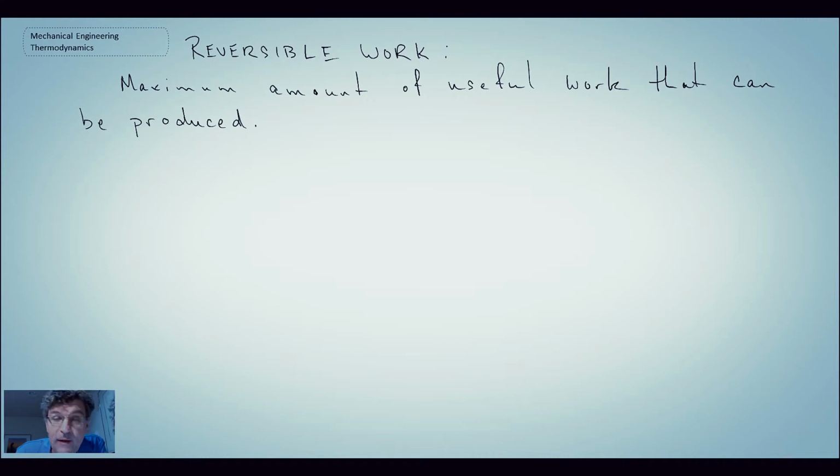So when we looked at the example of the Carnot heat engine a moment ago for the example problem, and we had the source at 1500 Kelvin, the amount of useful work coming out, or reversible work, was that from the Carnot efficiency. Another term that you'll hear discussed when we talk about exergy and exergy analysis is the term irreversibility.